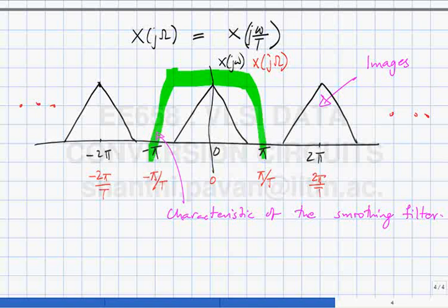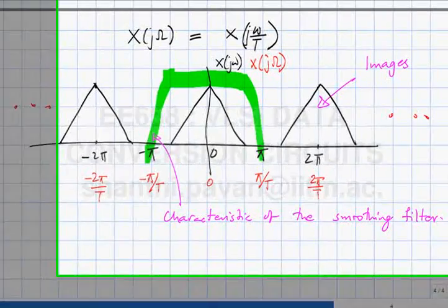There will be rough edges, which is basically something which is probably undesired. So to make the smoothing filter requirements easy, what they would do would be oversample the signal so that this digital signal occupies a bandwidth much smaller than pi, in which case the smoothing filter, the rate at which it falls off, can be modest.